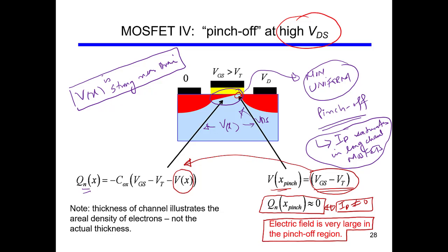So though the charge is very low, the velocity or electric field is very high, so the overall charge per unit time is the same. So it is the same throughout the channel. Okay, so you have to understand this, that although charge is nearly 0 near the pinch-off point, the current throughout the channel is constant.